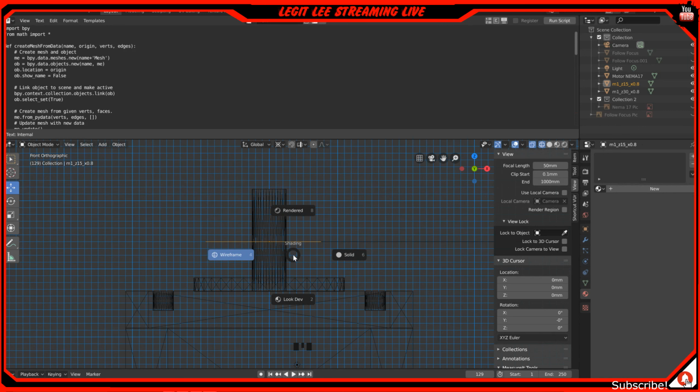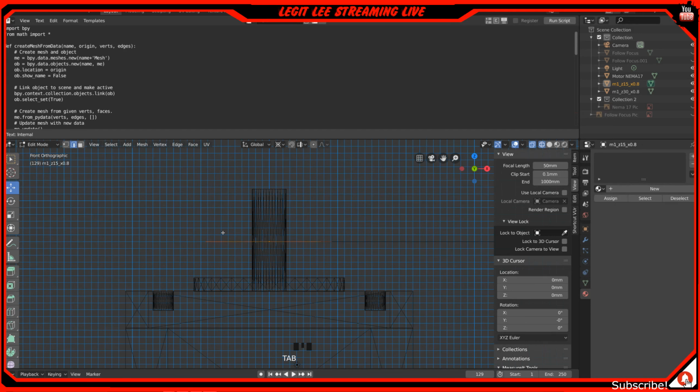What? That's weird. Oh, I can't do it. Hold on. I'm sorry, guys. I need to go into edit mode. That was my mistake. I was in object mode. Now we can hit E to extrude on the Z axis, and we'll pull it up.